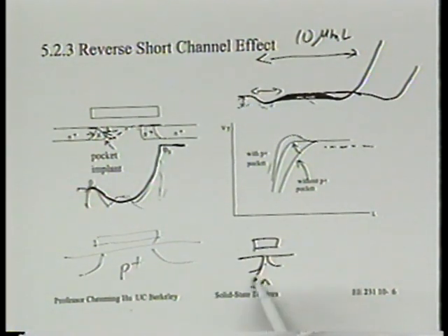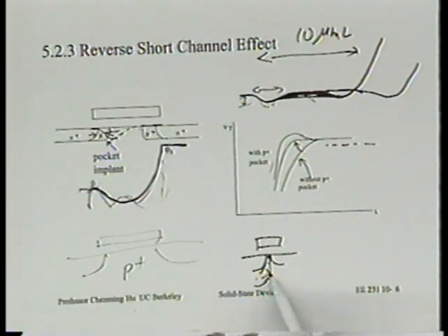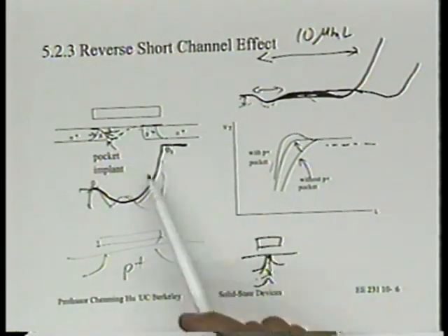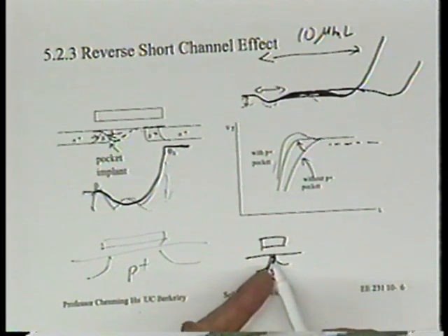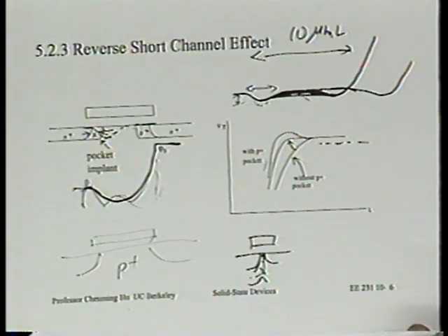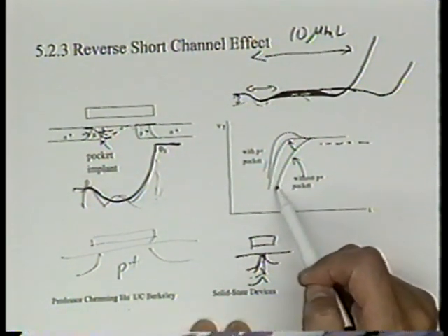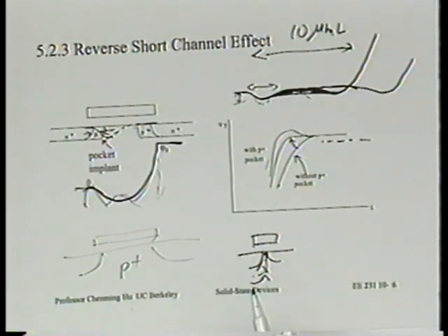But especially in this geometry, is this depletion region really determined by doping concentration, or is it determined by the junction depth? Right? So even this XD depletion really is not that much a function of the doping concentration in the pocket anymore. Can you visualize that? So given that's the fact, now using the model we talked about in the last lecture, can you see that eventually that VT fall off really is independent of doping concentration? So the fact that we have a P plus really have no impact on it. So you can almost see, finally this will catch up with that, with the original curve. You see that?